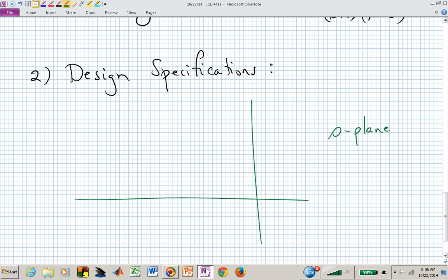And if it does, so that was 50-50. You could have flipped a coin, and half the time you would have gotten that answer right, yes or no. Yes is the answer. It does partition the S-plane. And how does it partition the S-plane? With what kind of a line? An angular line, a straight line, and is that straight line horizontal? Is it flat-lined, or is it up and vertical? It's vertical, isn't it? We now want to be to the left of some vertical line if we are actually concerned with some settling time specification.